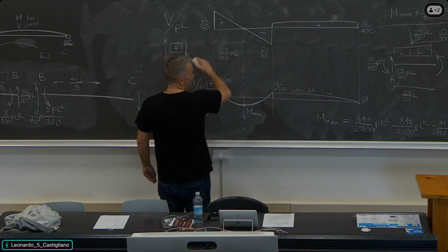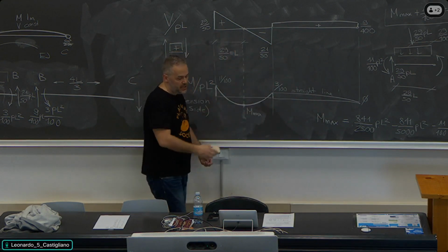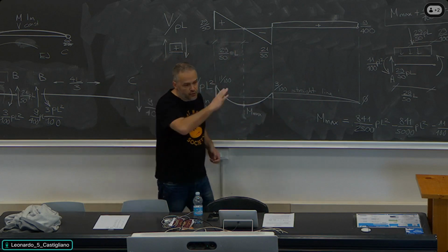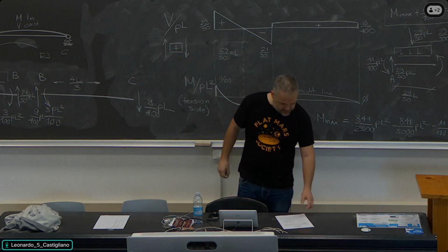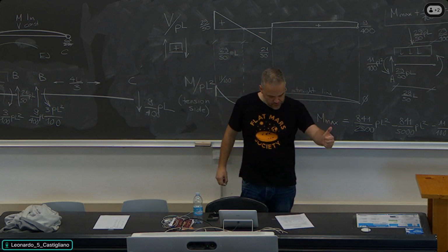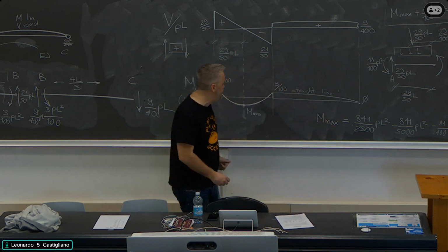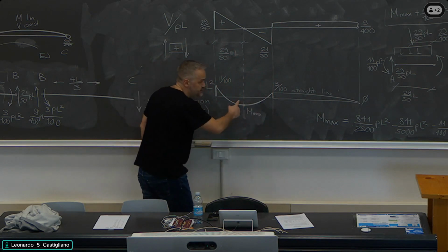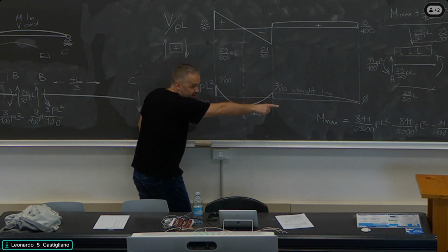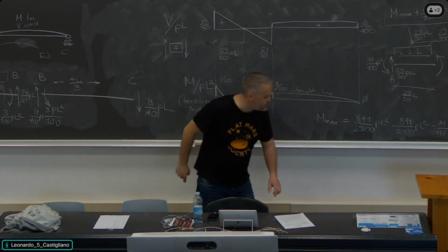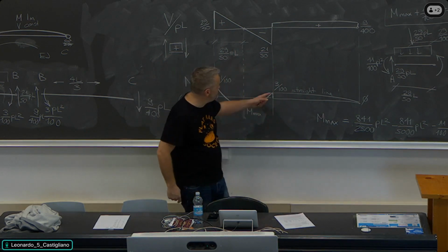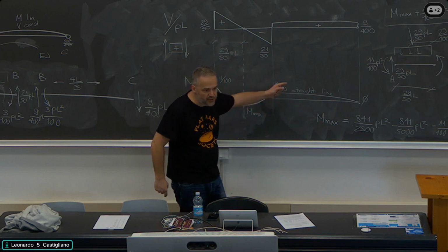Okay, you all have these values. More in detail, you will have the diagrams, you will check them, but keep in mind that we will have to design the longitudinal reinforcement at the bottom of the section, the point of maximum bending moment. So this value, which is over there, is relevant. Then the top of section B, so we will need the bending moment here, we know it.